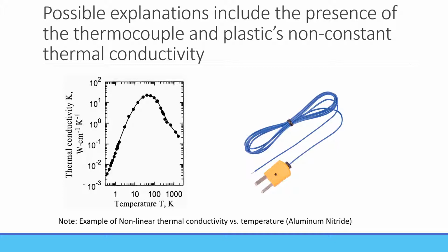And since we have such rapid cooling, the conductivity is changing rapidly. Now, the conductivity is not represented by the graph shown, but for many plastics it is similar. It's non-linear. It has a certain point at which the conductivity peaks and then drops off, and that's usually near